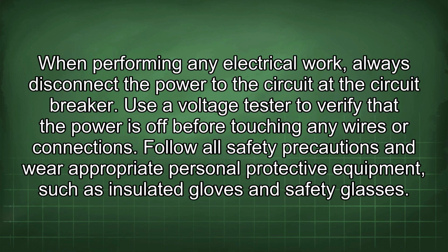When performing any electrical work, always disconnect the power to the circuit at the circuit breaker. Use a voltage tester to verify that the power is off before touching any wires or connections. Follow all safety precautions and wear appropriate personal protective equipment such as insulated gloves and safety glasses.